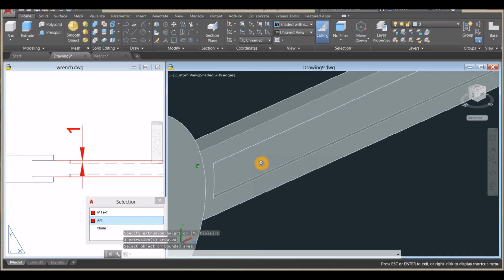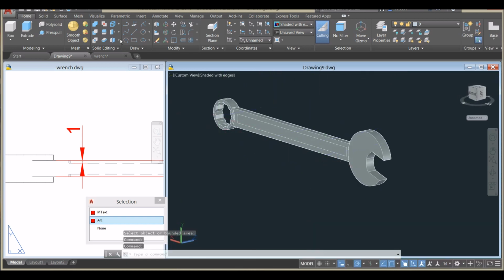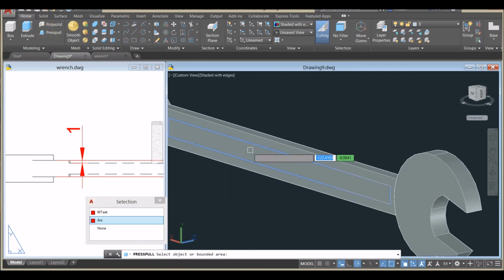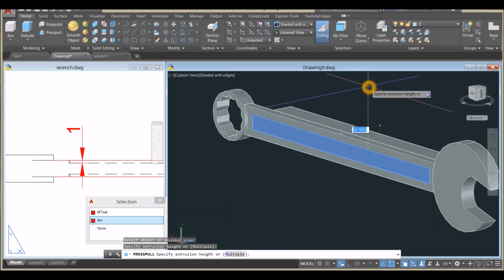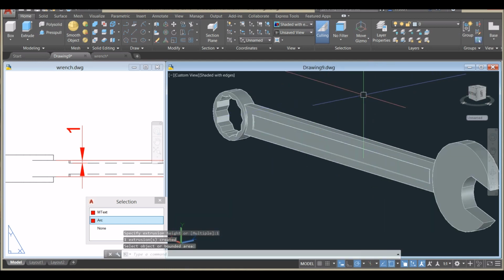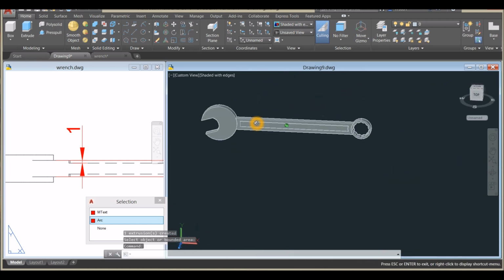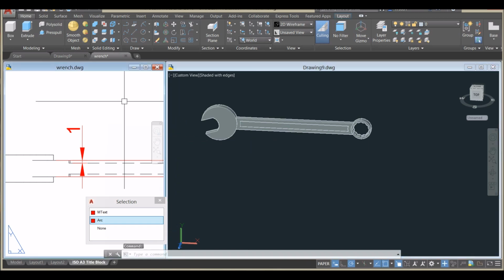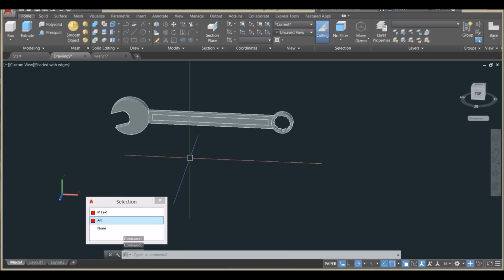As you can see, we've created indentation and turn it around. Same process. Press pull command, hover over this area, left click, move it to that direction or towards the center for 1 unit. There you go. Now I'm gonna join the objects. I don't think I need this one. Just minimize, maximize this one.